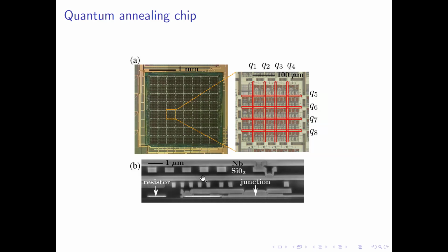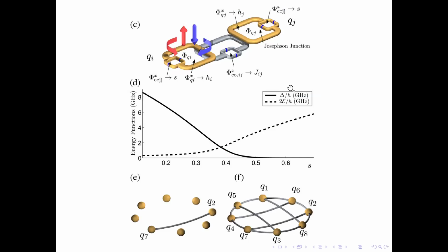So basically, you have niobium elements and SiO2 as the insulator substance. You are implementing a two-dimensional lattice of superconducting cables, and then you can have movement of vortices across that. And this is pretty much the way you can conduct the operations. So basically what you have here is superconducting loops, and there are Josephson junctions present. Then you can entangle two qubits with proper current delivered via time, and you can entangle various parts of these qubits. So it's shown how very different qubits can be entangled here.